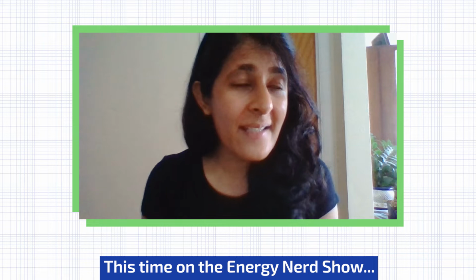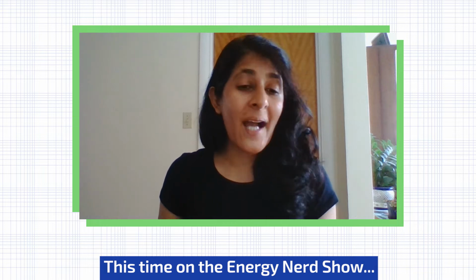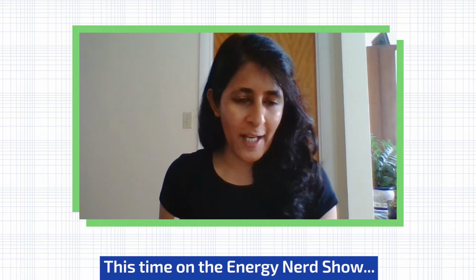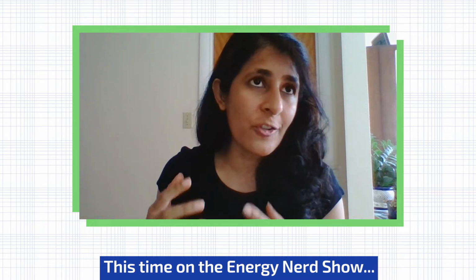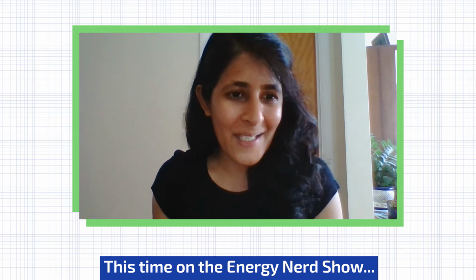So today we're talking about the value of distributed energy resources. The main technologies that are classified as distributed energy resources are energy efficiency measures, rooftop solar, and behind-the-meter storage. These are all distributed energy resources, and the customer can then avoid procuring that electricity from the grid. The key thing to remember is that the grid needs to be designed to accommodate the worst case scenario. So it needs to be designed for that maximum peak on the system. And so the higher that peak is going to be, the higher your infrastructure costs are going to be.